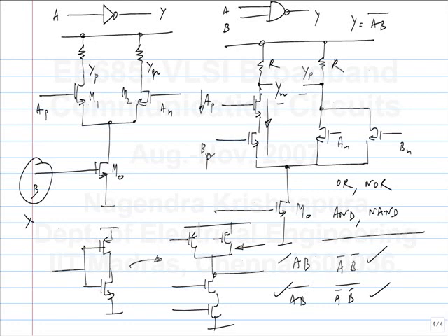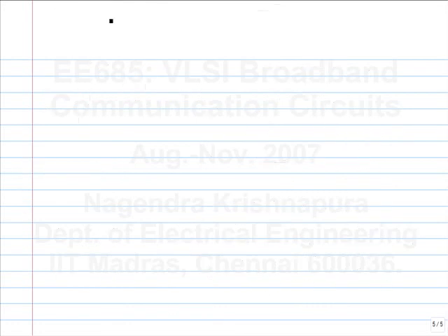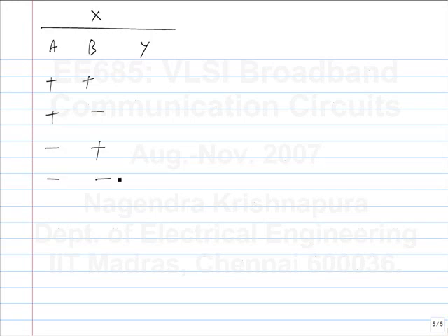So if I have to write the kind of truth table for a multiplier, this is a multiplier. Both inputs can be positive. These are the combinations. What do you get here? Plus, minus, minus, plus. So this is an XOR gate or an XNOR gate. So what you can implement with an analog multiplier is an XOR function, exclusive OR function. If the two have opposite polarities, which is like saying two have opposite logic states, the output will be in one way. If the two have the same logic state or the same sign, the output will be in the other way. Okay.